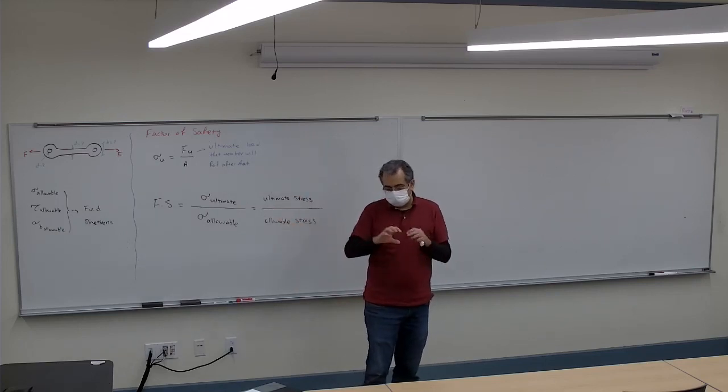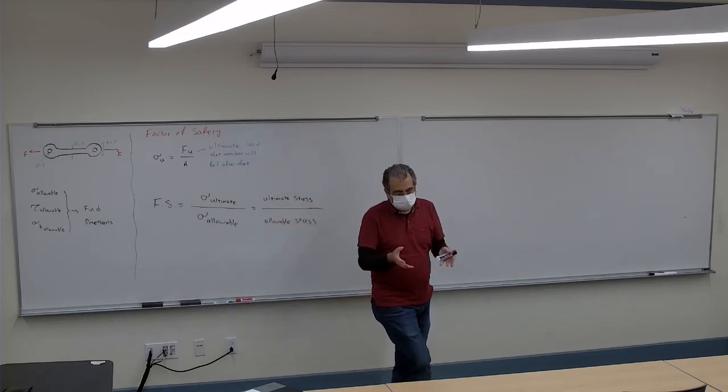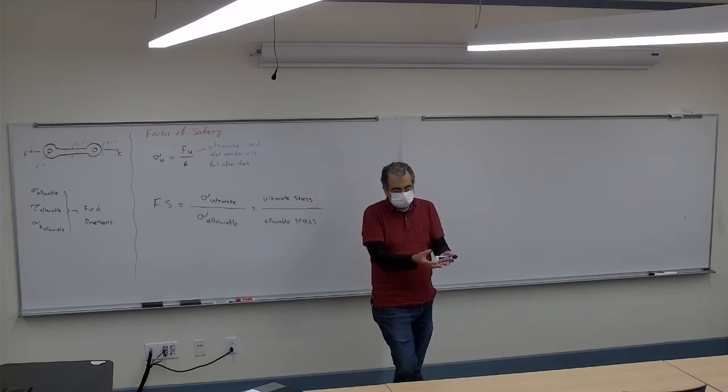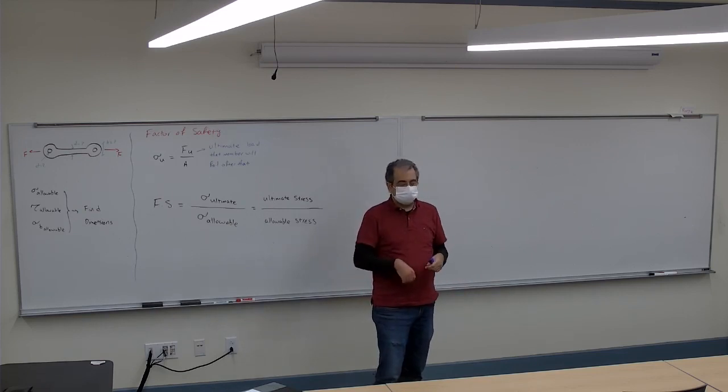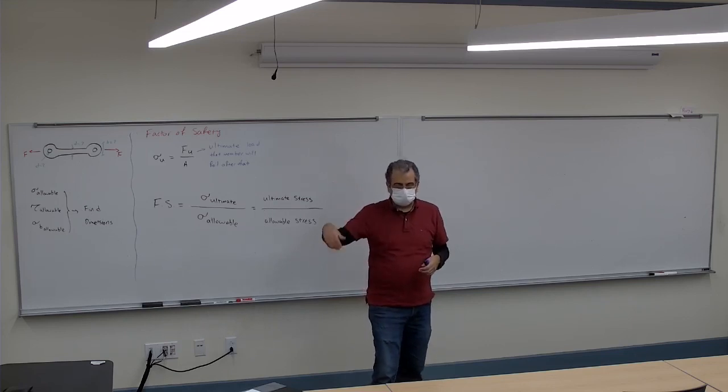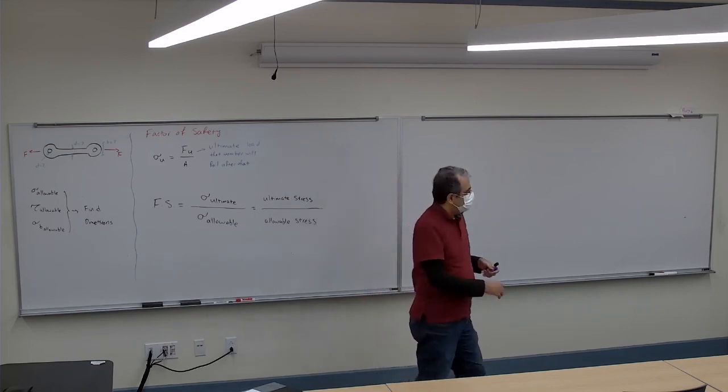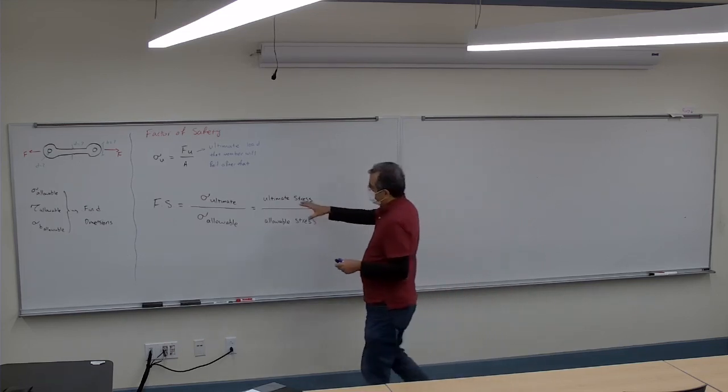So usually with those factors of safety, when you're building a single family home, okay, the worst case happens, the family is in there. So you're not going to make it very expensive. If it's schools, so many more students or people are there, so it should be higher, and for the hospital, higher than that. So this is what you're going to decide about that.